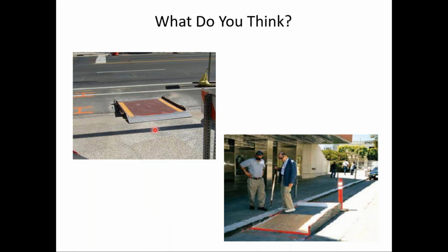One is that you can make those almost any slope you want, so they might be steeper than 8.3%. But in this case, a bigger concern is, notice, what does someone do, or where does someone go after they go down the ramp? There's no channelization to direct the pedestrians where to go. So that's my big concern with this: once pedestrians are in the street, there's not much guidance provided that I can see in terms of how to proceed or where to go, or there needs to be some separation between the pedestrians and the vehicular traffic.